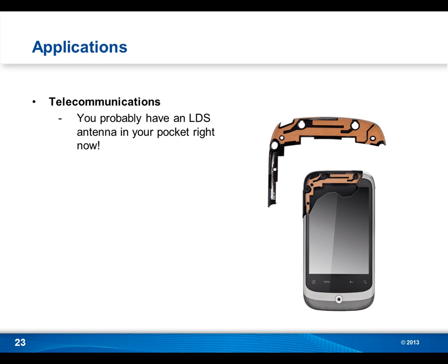The smartphone industry really embraced the LDS technology, or the MIDs with LDS technology, very much so. And there's a couple of reasons why it's so attractive for this particular industry. One of them is the human form factor. We try to put all these different functions into a phone these days, but our hands are not getting any bigger. So we have 5, 6, 7 or more antennas in these phones, and we need to keep them separated. So we have to use the space that's at hand, literally, no pun intended.